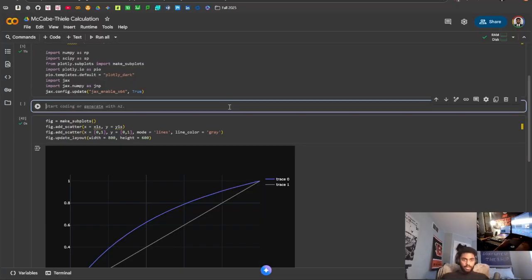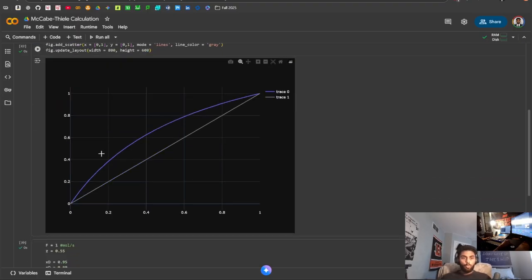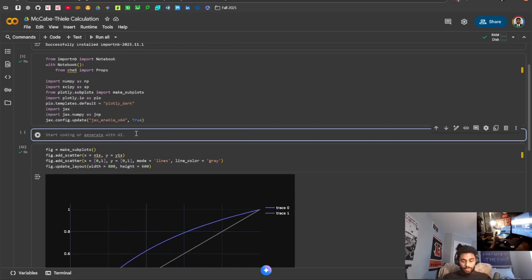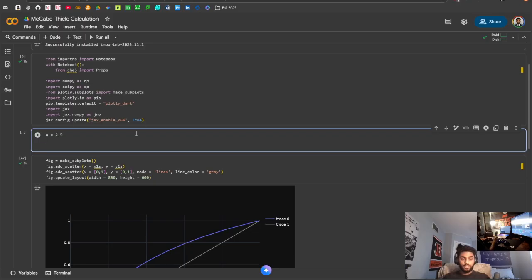So really quickly, I kind of want to go over how we can construct this kind of bare bones XY diagram, not using our bubble points and dew points, but rather using relative volatility. So this measure of relative volatility is something that we can use to relate our vapor composition to our liquid composition, and that's something that I've derived in the previous video. And that relationship looks something like this.